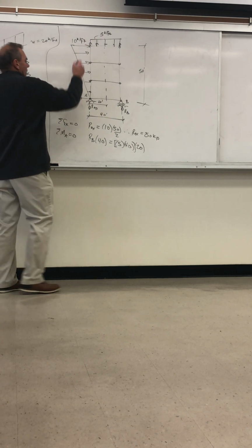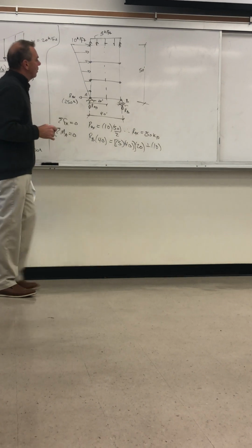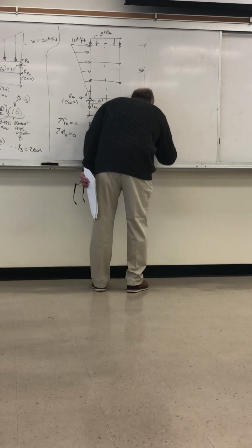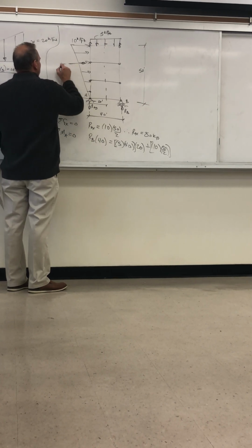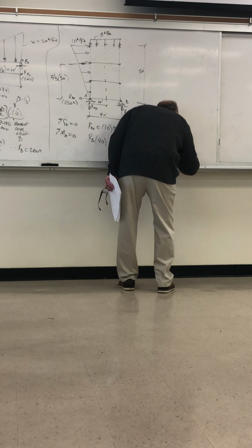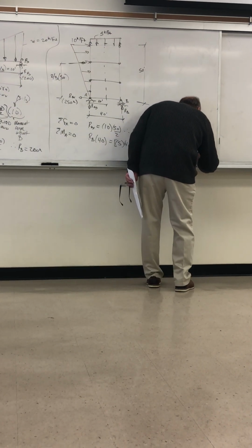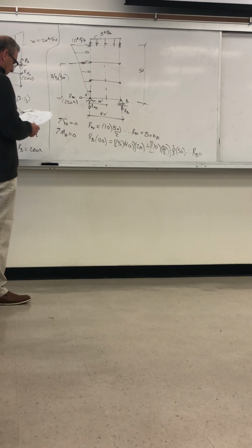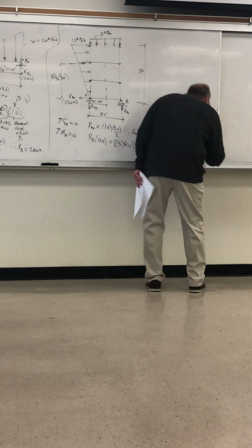And then I have this distributed load. I say plus 10 kips per foot, to the total load now to the right. Applied load is 10 times 50 over 2. And then multiplied by the distance to the centroid, which is 2/3 of the height, which is 50, right? That's my moment arm for that load. So times 2/3. And then the only unknown is R sub B. These twos cancel, it simplifies a little, and then you solve for this: 308 kips.